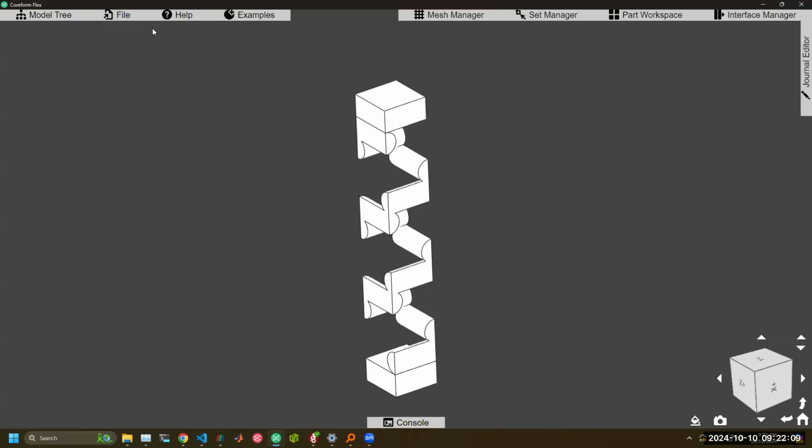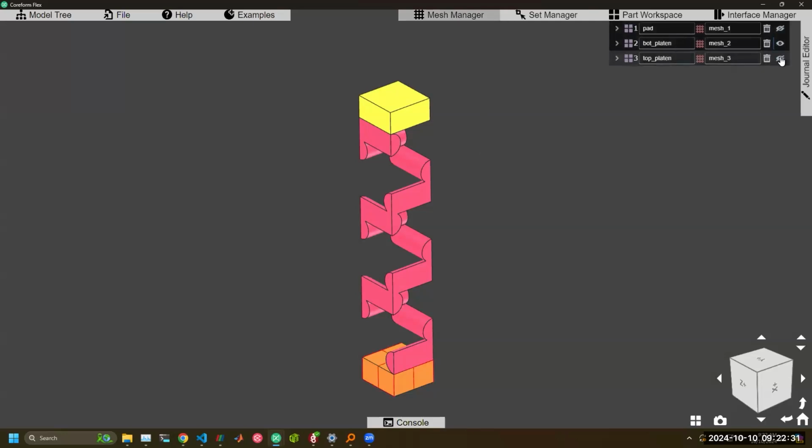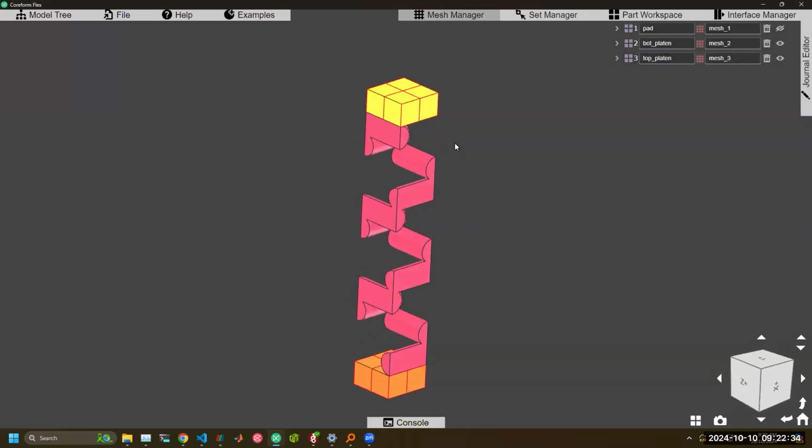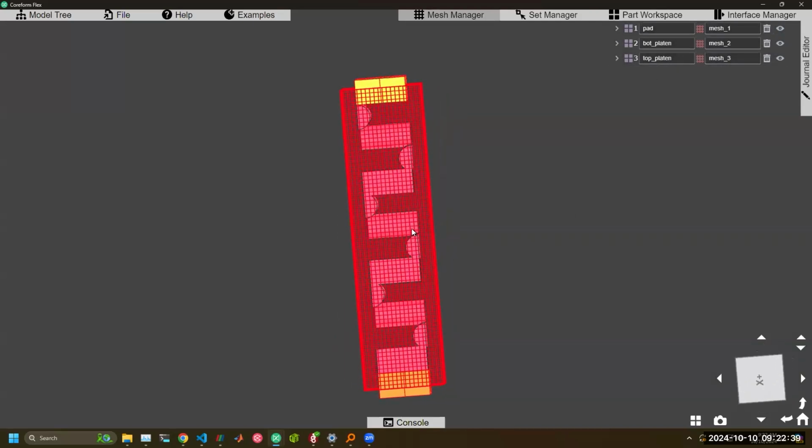But what I wanted to point out is that Coreform Flex not only supports the immersed approach, but also cases where meshing is trivial. So for these, I just color here by part, for the orange and yellow regions, there's no reason to have to immerse those in a box. Those can just be automatically body fit. And so what we'll see in our meshes is we can produce body fit meshes on those regions, as well as an immersed mesh on the difficult to mesh regions. And that's a good compromise between performance of the solve and of model setup time.